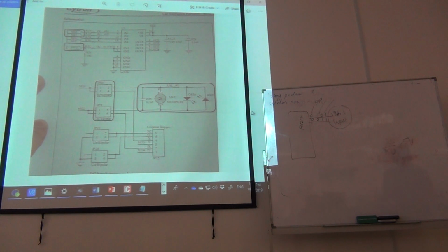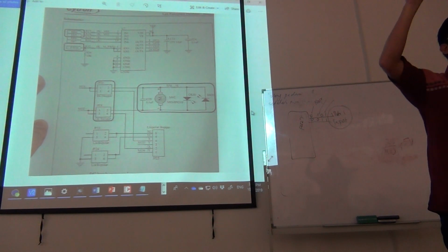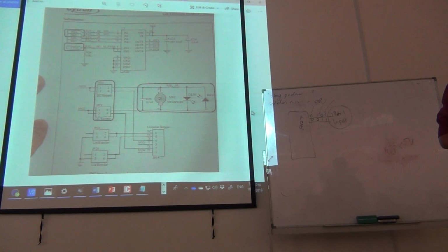Okay, try to understand. So right now there are two things that you need to understand carefully. PWM is to control the speed, and the H-bridge driver is going to be used to control the directions. But of course, you require this H-bridge to make it work, because you cannot simply run your motor without an H-bridge. You cannot connect your CCP enable pins to the motor, because your motor has only 2 outputs. That's why you will require a driver. So this driver can control your speed and your direction according to your PIC programming.